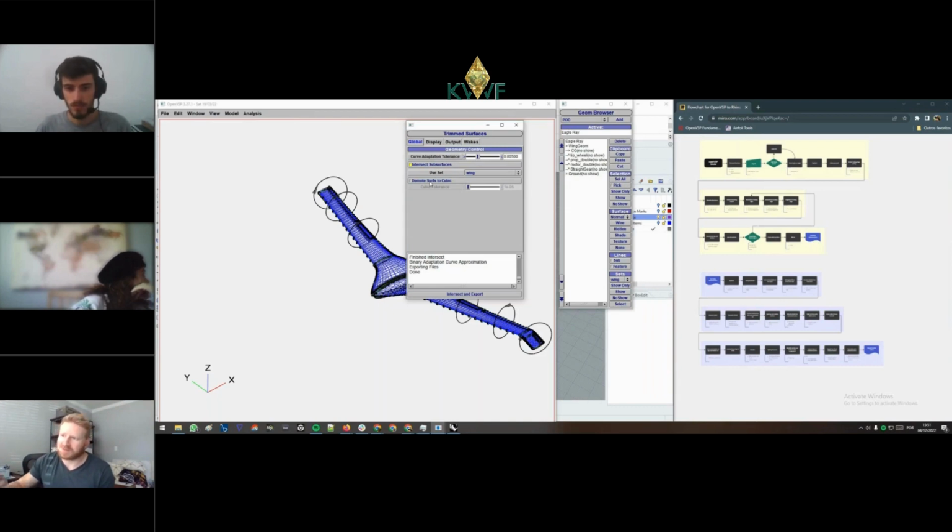And so if you can avoid things like CAD programs ringing through surfaces or these little oscillations that can happen, down the road in wind tunnel experiments or even in flight, you can see the flow pop off because of these little oscillations, and they can come back and bite you.